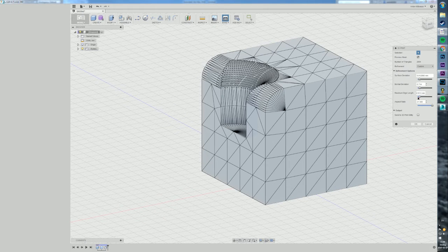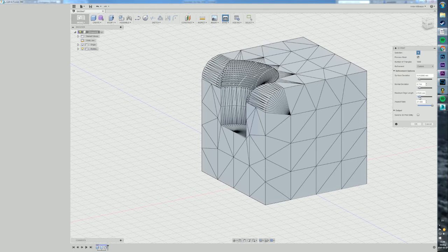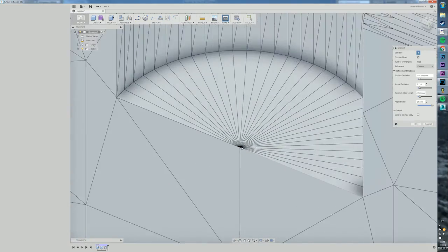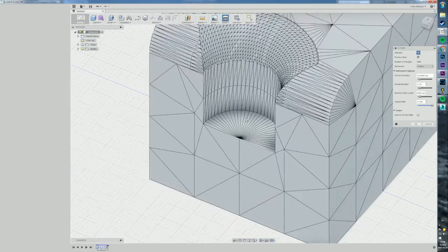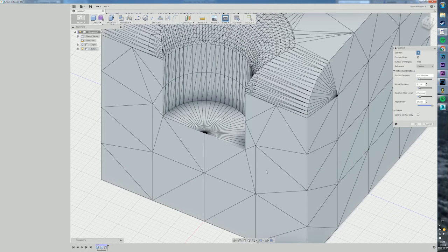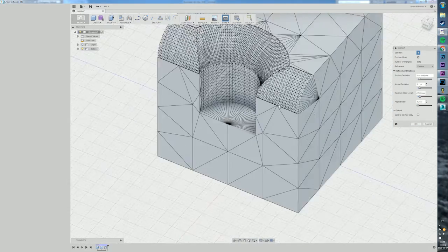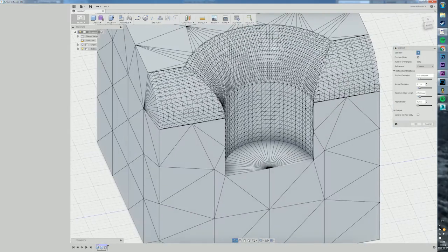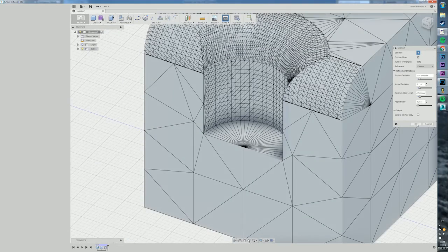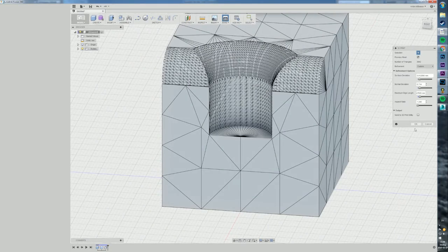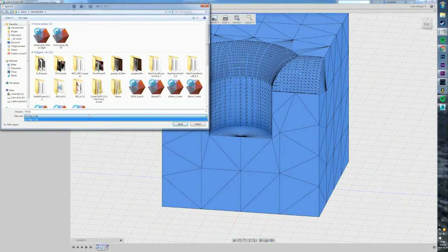more edges here. I think that can be pretty good sometimes, just to have a better flow. You see here how everything is connected and it only consists of different triangles. Aspect ratio, yeah, sure, you can add some details here on the curvature as well, just to have more details. More details is usually better. So this is now an exportable 3D model. So you can now export this as an STL file.